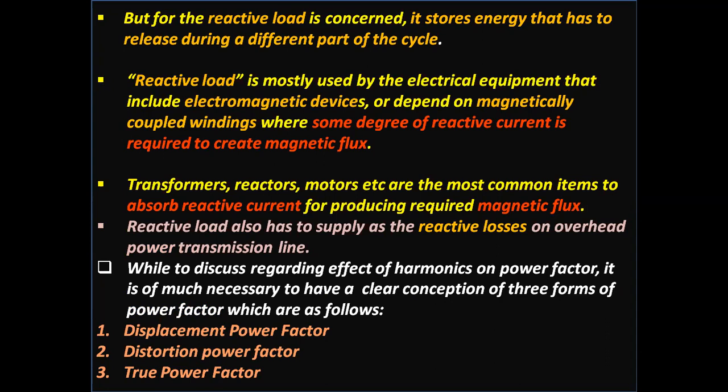Transformers, reactors, motors, etc. are the most common items to absorb reactive power, that is reactive current, for producing the required magnetic flux. Reactive load also has to supply the reactive losses on overhead power transmission lines.